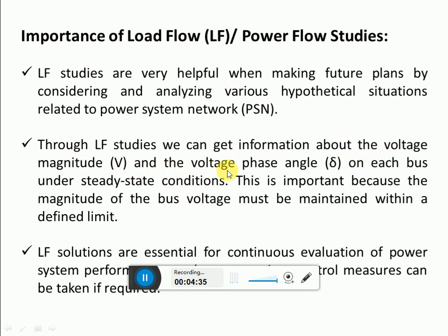Now as we know, the load flow analysis gives us information about voltage magnitude and voltage phase angle on each bus under steady state conditions, and this is important because the magnitude of the bus voltage must be maintained within a defined limit. Otherwise, what will happen? Voltage collapse or voltage stability problems will arise.